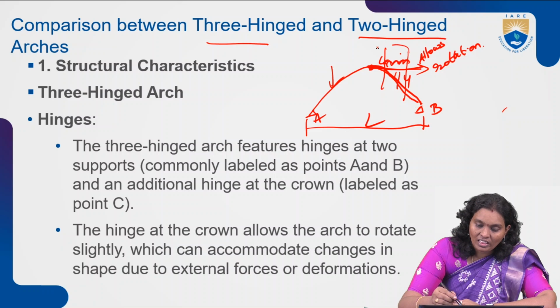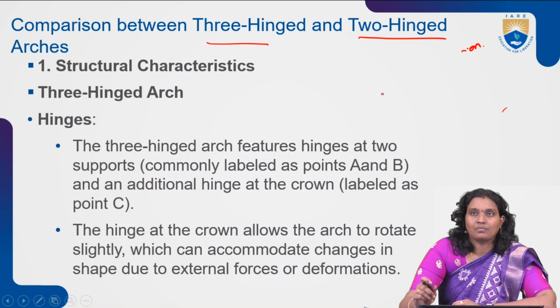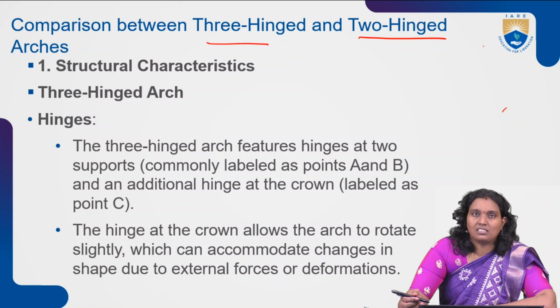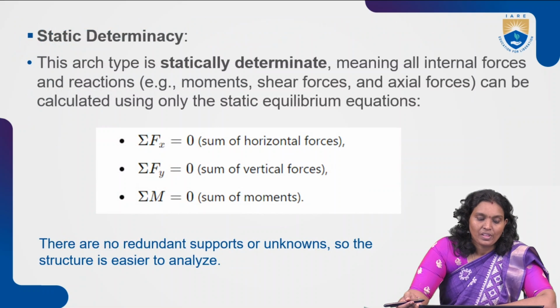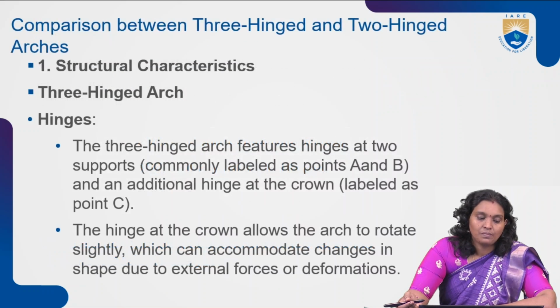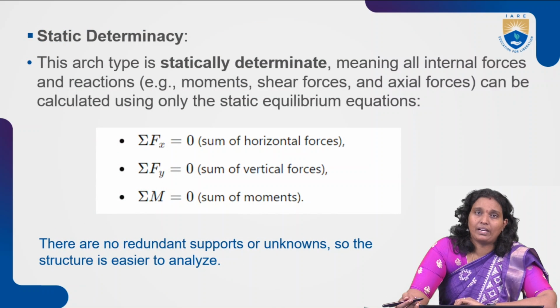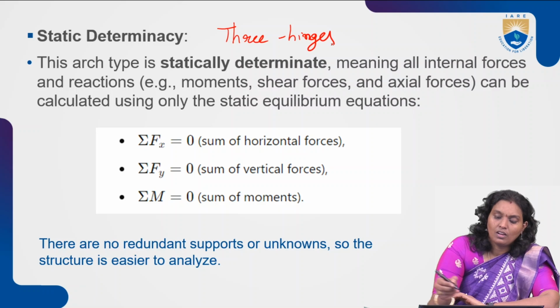So according to all these changes, we are going to understand that in these three-hinged arches, it allows that slight rotation. So this is one of the structural characteristics. Some of the structural characteristics we may understand in these hinges, especially for these three-hinged arches, is that they are statically determinate. So this three-hinged arch type is statically determinate, because for knowing about these internal forces or reactions,